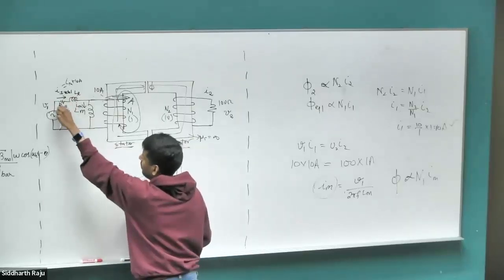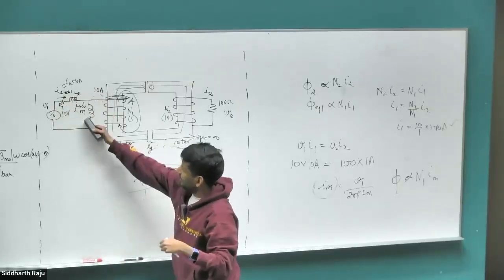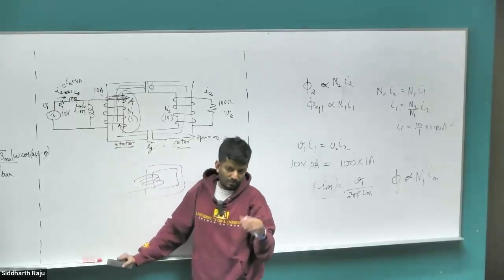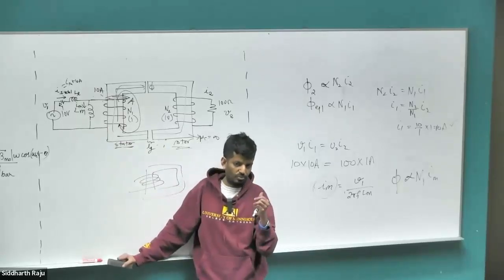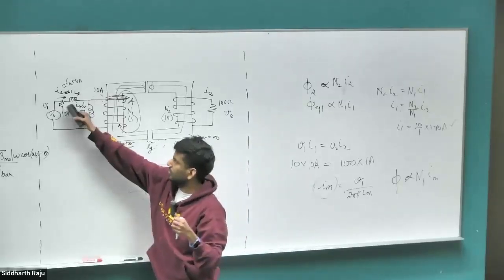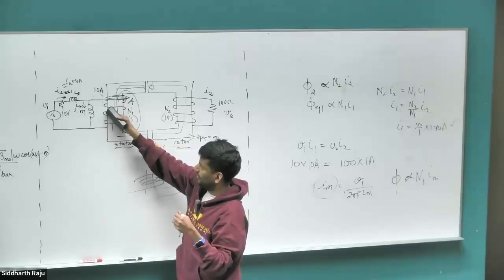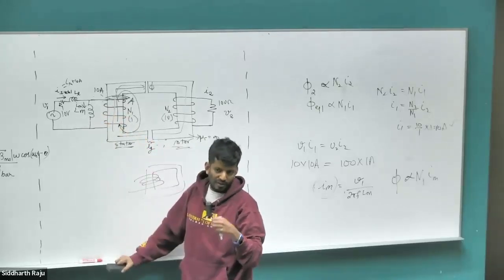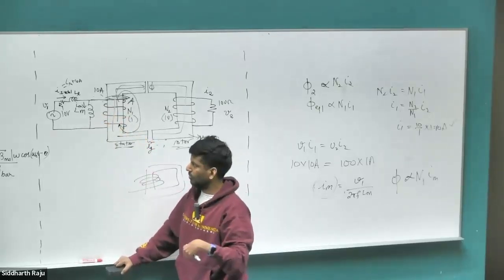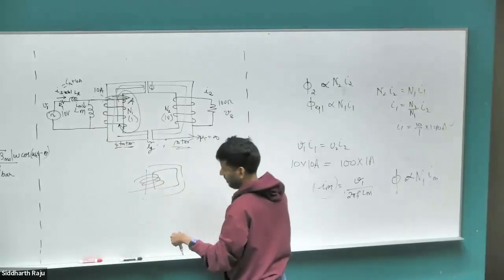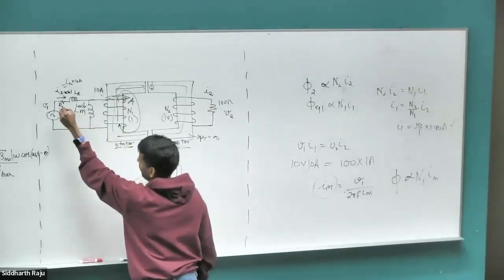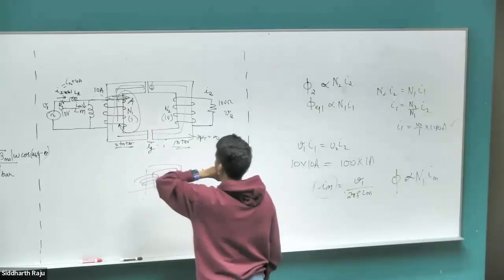and the same reason for the resistance. Why did we put the resistance on here and not here? Because the current that created the magnetic field in the first place is also going to get dropped across the coil as it flows through the coil. Right? If you put the resistance here, it will only drop the current due to the secondary current being reflected on the primary, but not due to the magnetizing current itself, which again is going to go through some wire and drop the value across there. So in our equivalent circuit, these two terms come on the left, and then we have a magnetizing inductance.